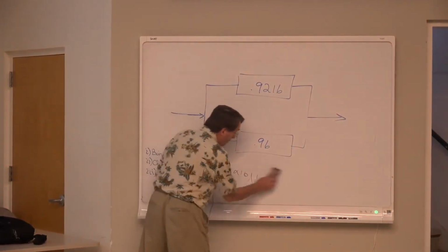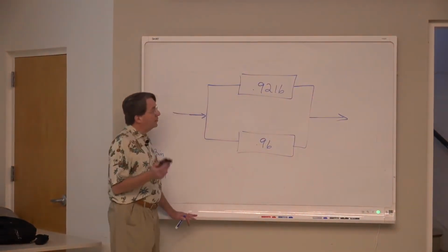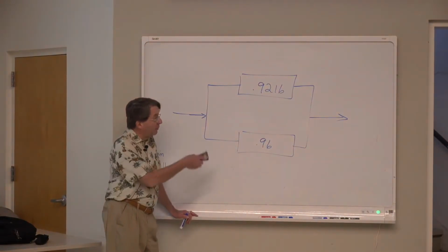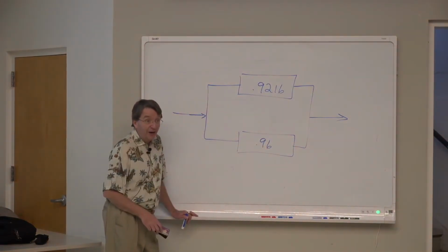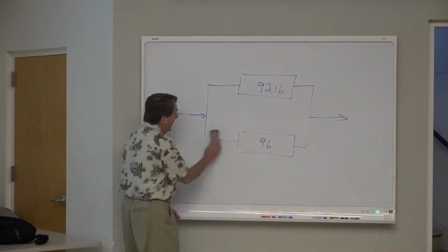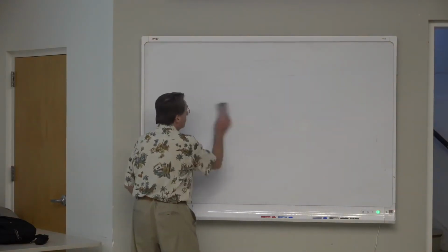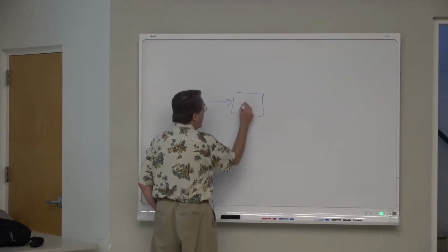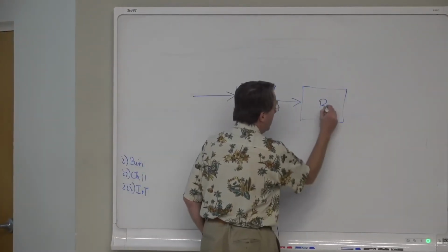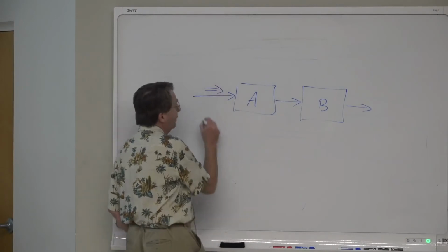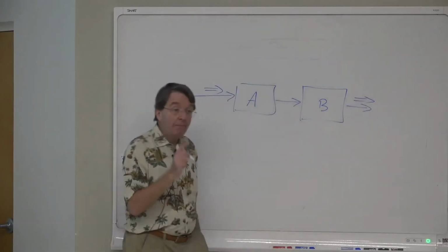Correct. Can I just repeat that? Because Alexandra's question is pointing out we did a pretty good job of understanding how sensors work in parallel. Now, if we were to just look at series sensors, so you have sensor A connected to sensor B, the only way I get from the input to the output is that both of them work.